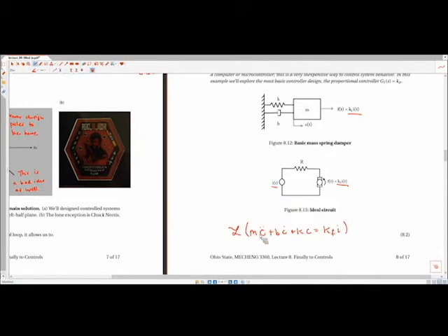So I guess I will say this, is that everything that we're going to learn from looking at the transfer function, we can apply to the cases where we have non-zero initial conditions. With respect to that, we expect the control system to drive the system to some sort of reference position. So if it has some sort of initial velocity to it, and our reference says do not have initial velocity, it's going to eventually drive it to some sort of no velocity.